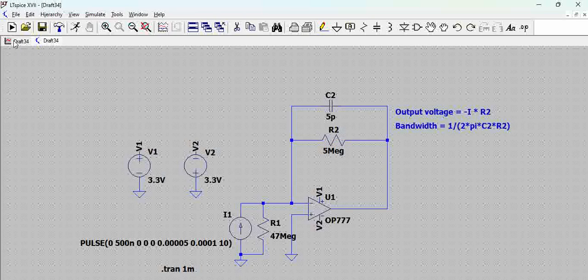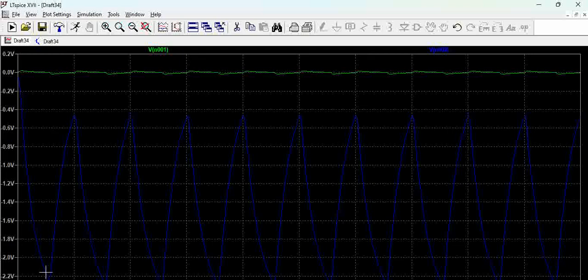So the output you see here is on the negative side, right? So it goes up to minus 2.5, and then once the input reaches 0, because the input is a pulsed input, right? It's not a continuous 20 millivolts. So that is why you see a fluctuation on the output corresponding to the input voltage here, which is explainable, right?